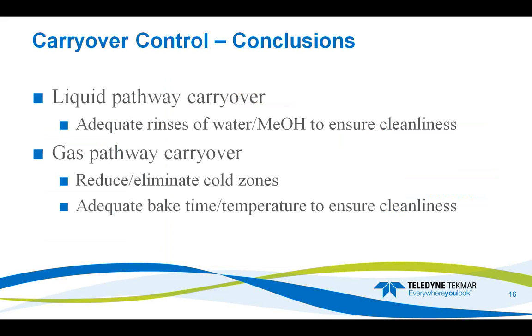So what are our conclusions on carryover control? For liquid pathway carryover, we want to make sure that we use adequate rinses of water, including methanol if necessary or when necessary, and making sure that those rinses are working properly. So the water is being transferred over to the sparger, making sure that it's hot. So even just touching your sparger as your water is being carried over, do you feel it warming up? Is that hot water that's coming in there?